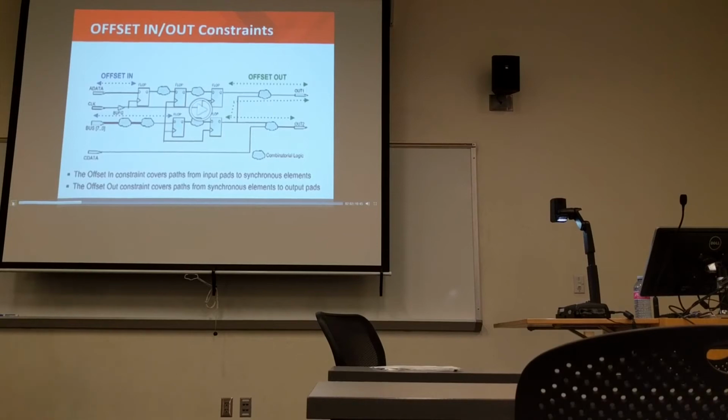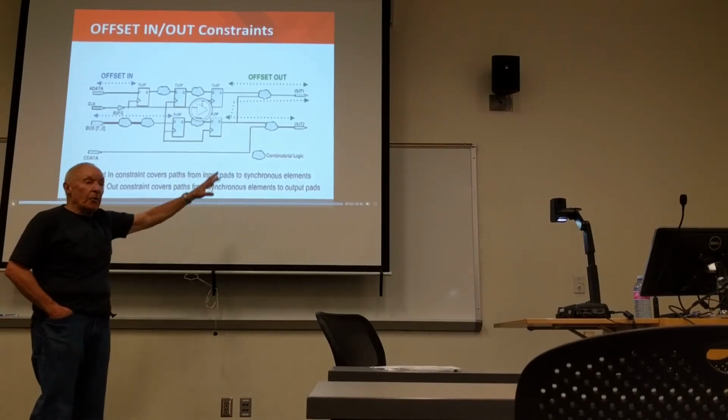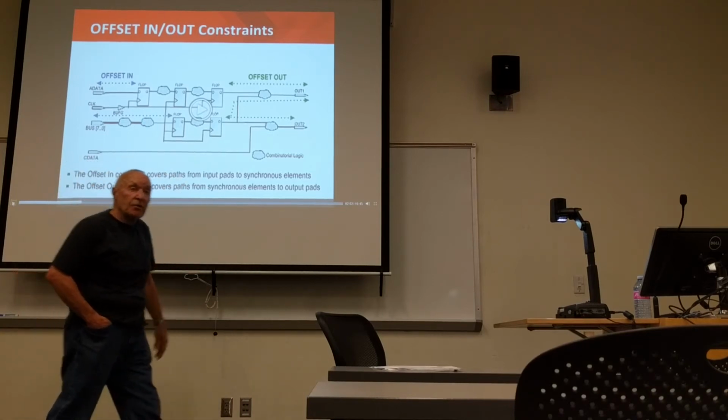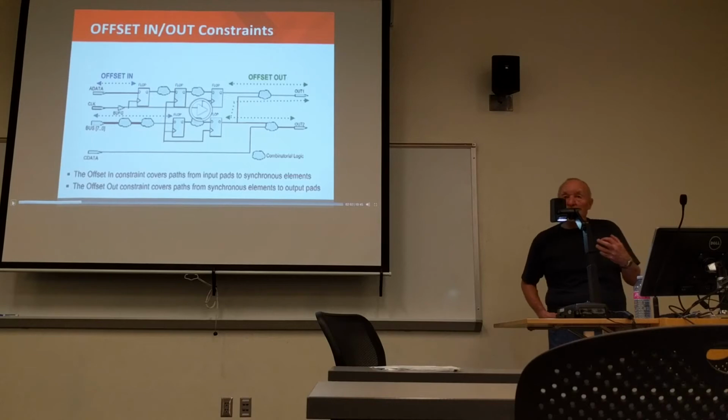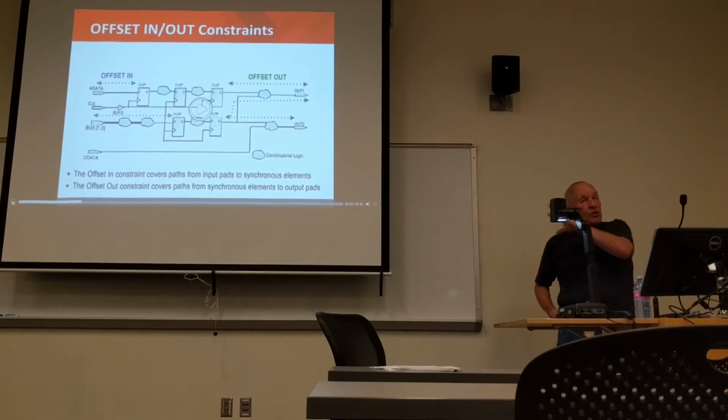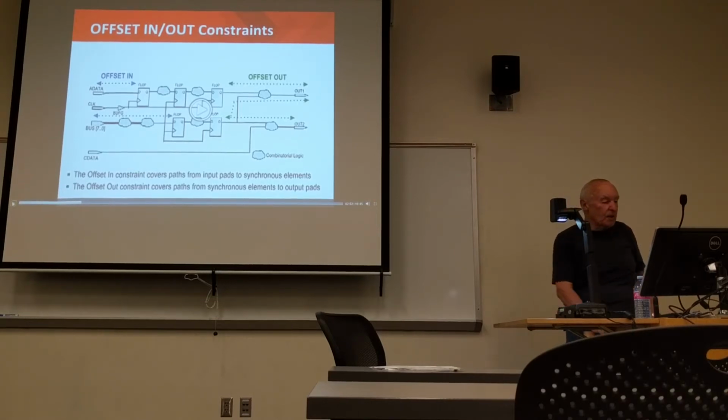So you're going to specify, if you will, input propagation delay, output propagation delay, and a period constraint. And then the timing report that you get, once you specify what your constraints are, will generate a separate entry for every timing violation it found. And we're going to take a look at some of those shortly.